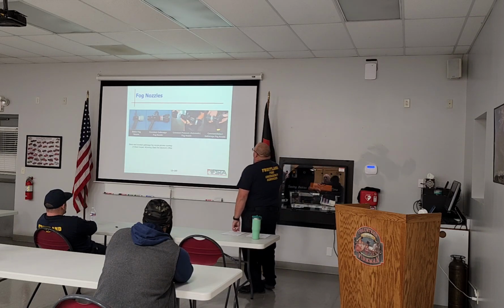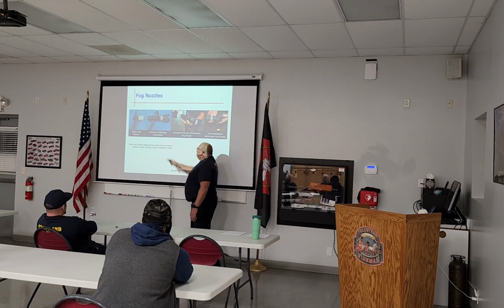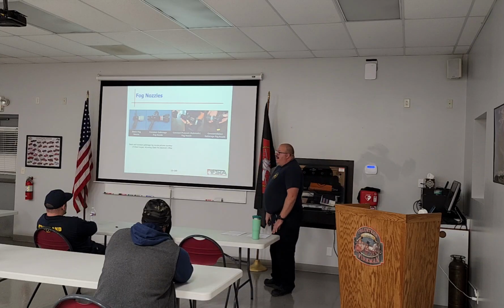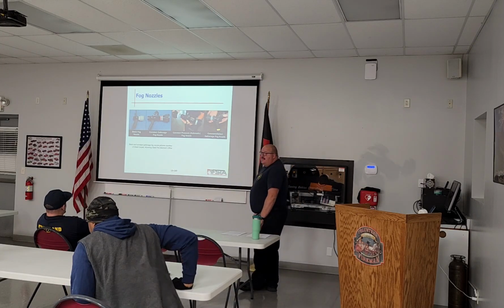Fog nozzles. So here are some examples of them. You have a basic fog nozzle, you have a constant gallonage fog nozzle, a constant pressure, which is an automatic fog nozzle, and a constant select gallonage fog nozzle. We have these three on our trucks. That basic fog nozzle, I've never seen it, but apparently it exists somewhere in the world.